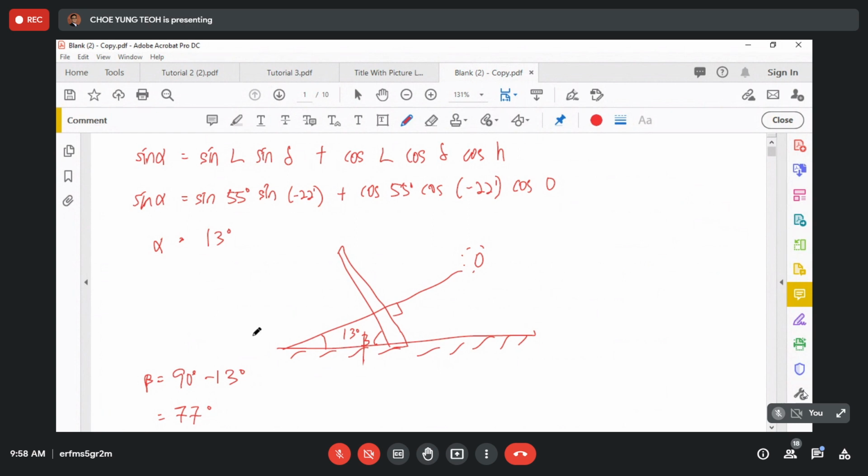Of course, let's say you do not know the day. In a real situation, you just refer to the direction and length of the shadow. Then you can identify the angle and set the tilt angle. Just face the direction of the sun, which means the shadow is always at the back. That's the idea for the real case. But if you are not there, you cannot do this kind of experiment, so you still have to do the calculation.